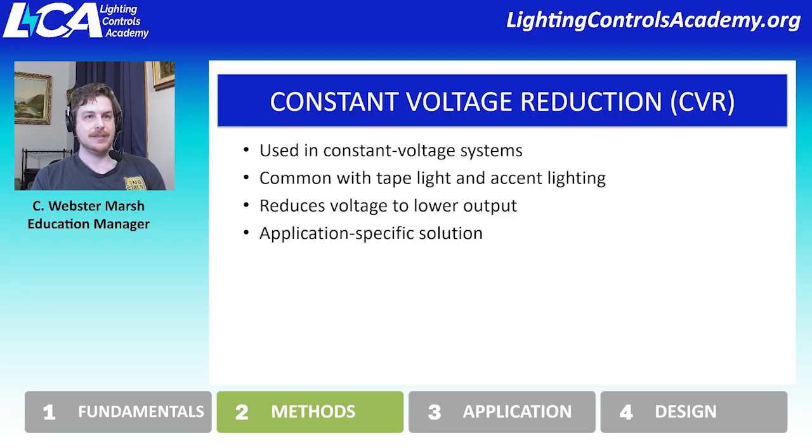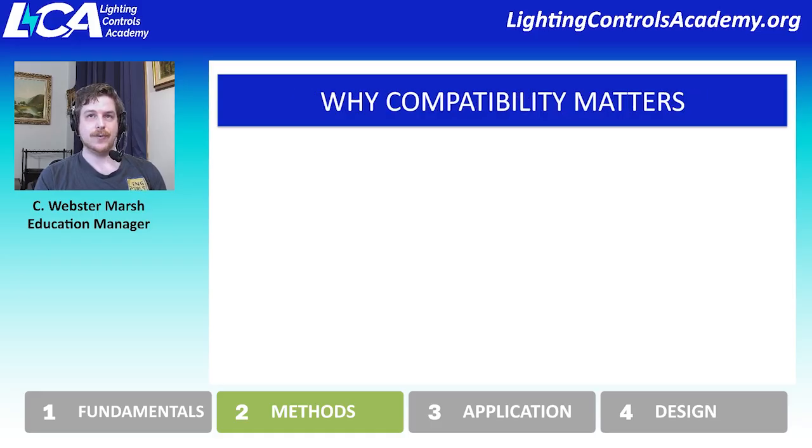It is application specific typically, though, so it's really important to keep in mind that if you are picking a driver, to check with the manufacturer and ask, what's going to work better with this diode, because you can't just connect any diode to any driver and expect high quality performance. So making sure that you've aligned, whether it's CCR, CVR, or PWM, to the fixture and the diodes is going to be important to that selection. But in a lot of cases, manufacturers will provide recommended drivers before you even get to that point.